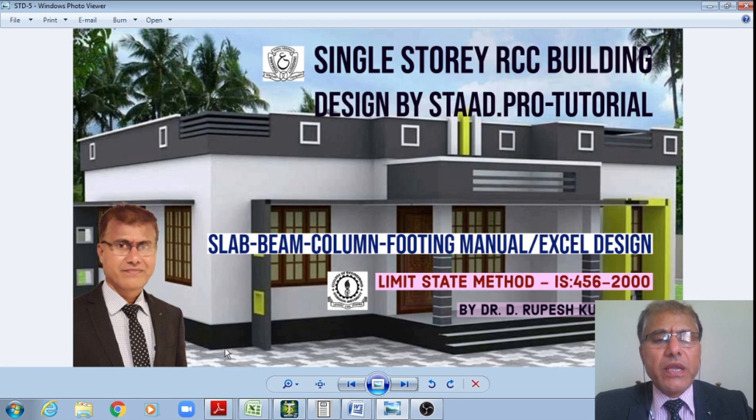That is my assumption. Below that it is presumed that I do have sufficient safe bearing capacity of 200 kN per meter square. Therefore the columns are embedded in the footing, which is having an SBC of 200 kN per meter square, right.